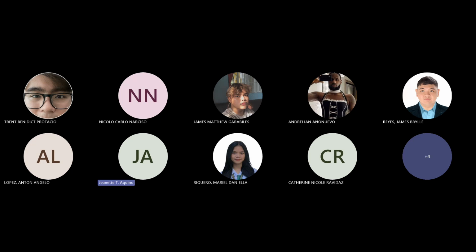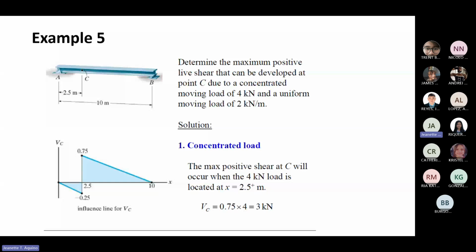So the influence line for shear is what we're using. We just apply it: the maximum positive shear at C will occur when the 4 kilonewton load is at that point. So VC is equal to 0.75, this one, times 4, equals 3 kilonewton.